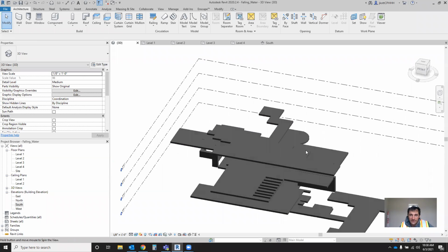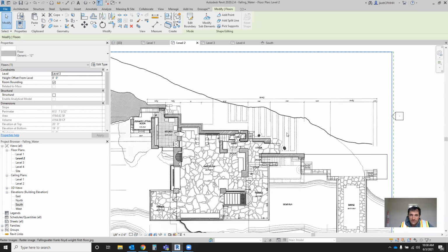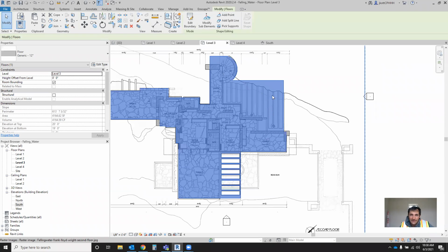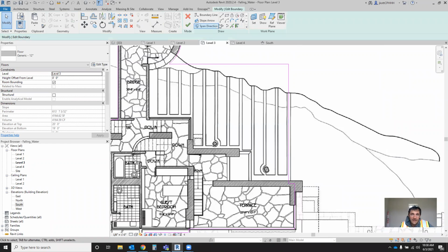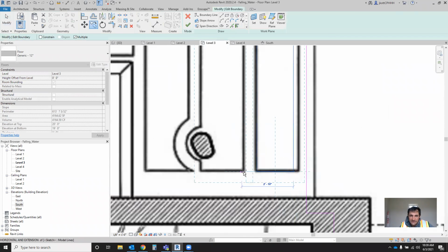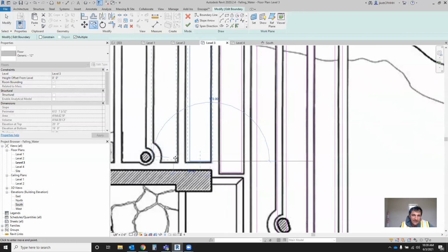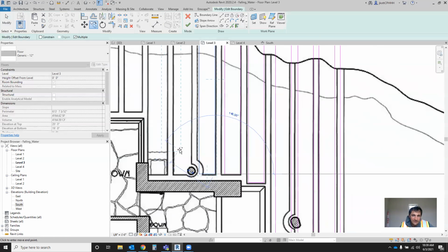So I'm just going to come back in here and just talk a little bit about this last area. Similarly to this piece, we want to add in these louvers. So we will do that like so. All right, and press tab, it will select all. And we're just going to copy multiple instances like this across this awning piece that is connected to the 3rd floor. You can see the gutter in it. We're going to move that out.